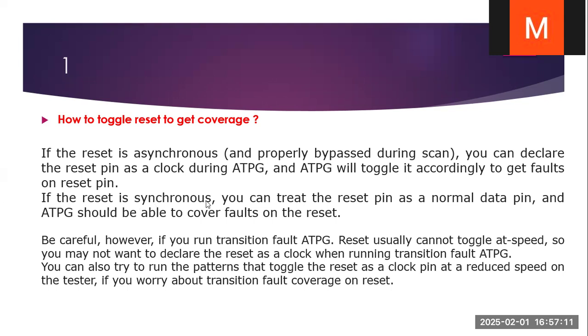If reset is synchronous, you can treat the reset pin as a normal data pin, and ATPG should be able to cover faults on reset. Here one caution, be careful. If you run transition fault ATPG, reset usually cannot toggle at speed.